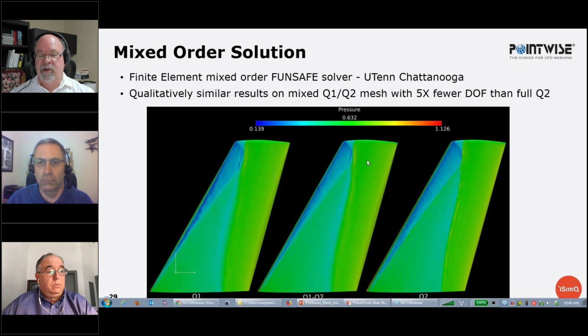And I think adaptation is really the great equalizer. What we've seen in a number of cases we've tried is, even if you start with a not so good mesh, maybe you have a mesh where at the top of the boundary layer into the volume mesh above that, there's a big jump in mesh size, which is difficult to control most of the time. But as soon as you start adapting, that jump is attacked. And then you have a smooth progression in your mesh length scales as you go from the top of your boundary layer into the volume. So in a way, it attacks these kinds of deficiencies as well.